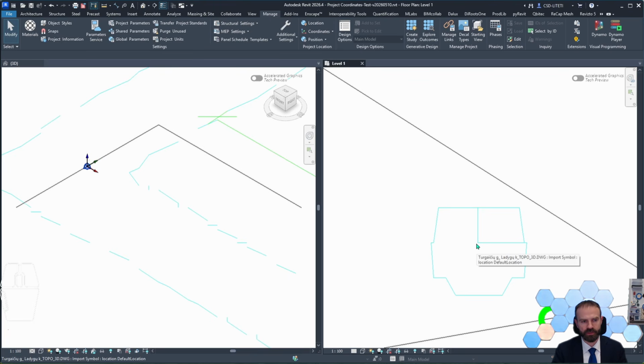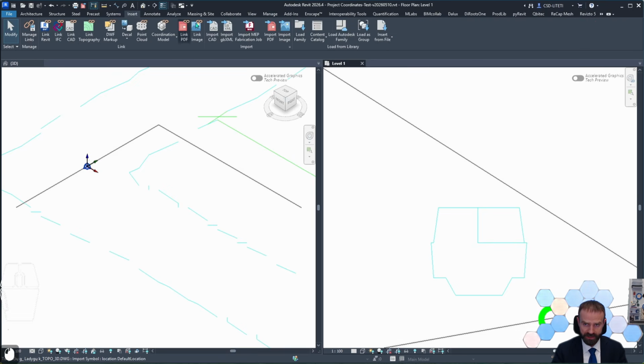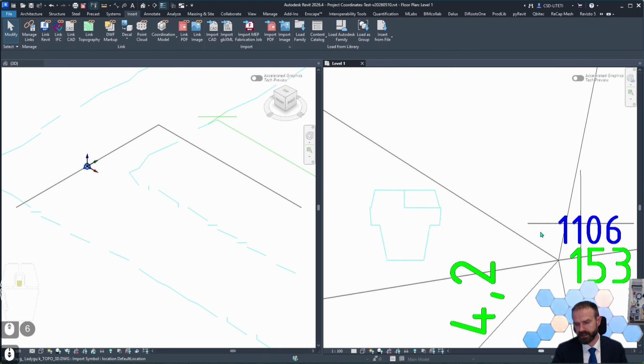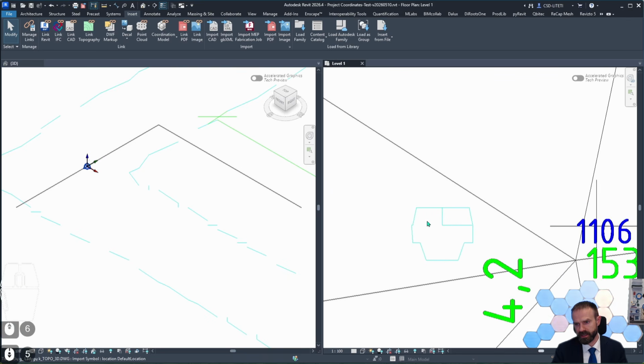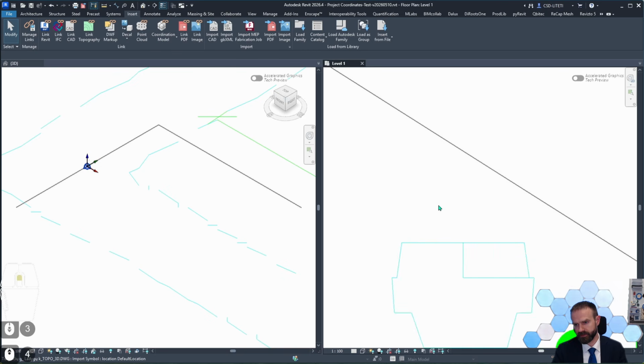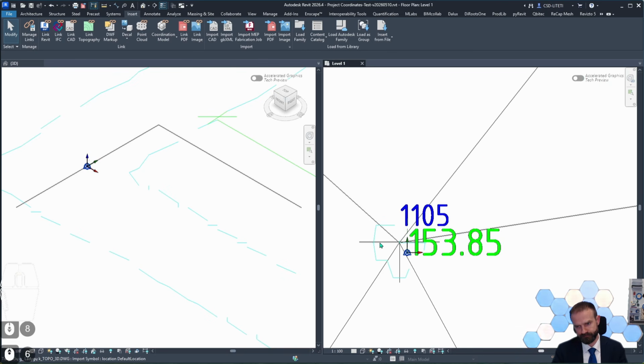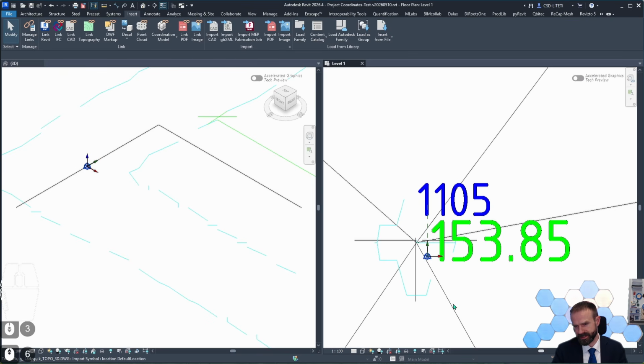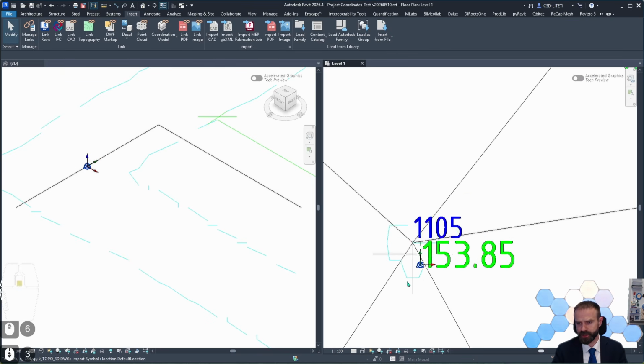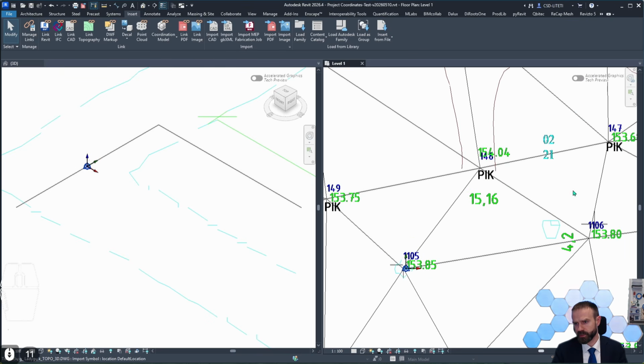So basically you need to insert all data using the insert tool inside the local coordinate system of a project. If you insert objects in global coordinate systems, you will have a result looking like this. Circles are modified and you can see the shape is totally broken.